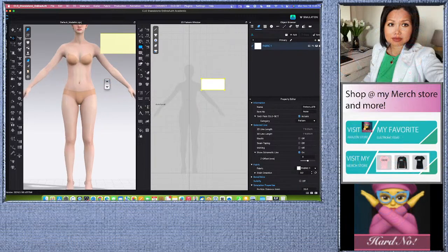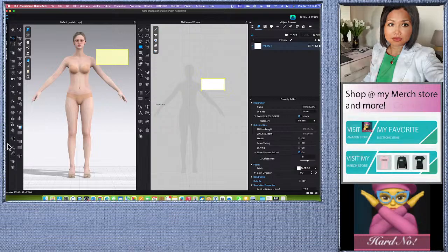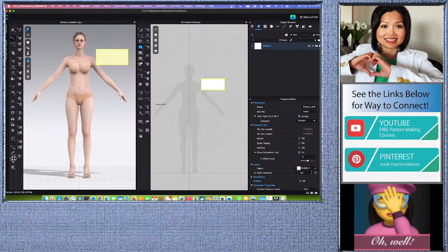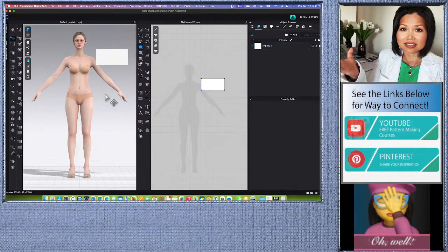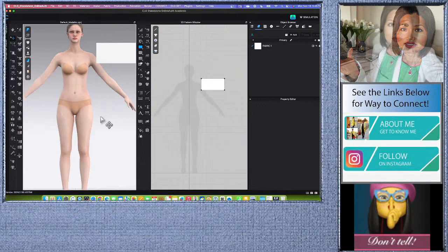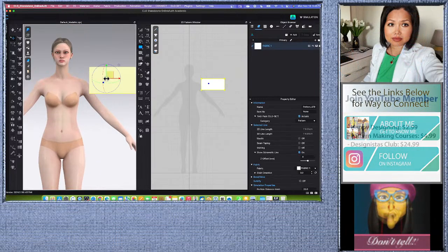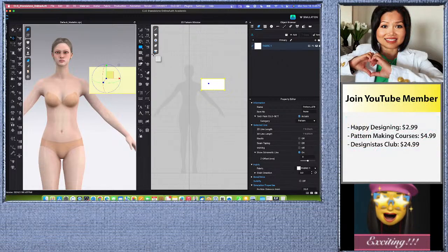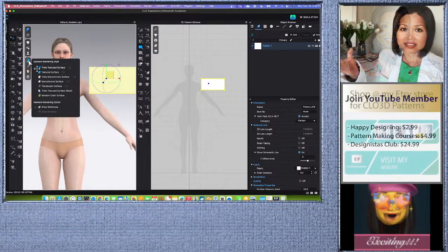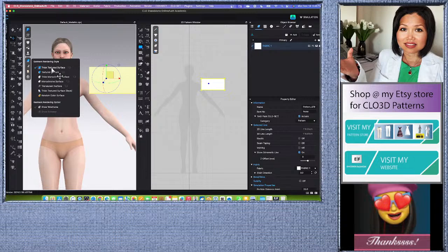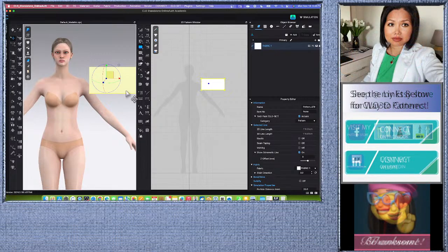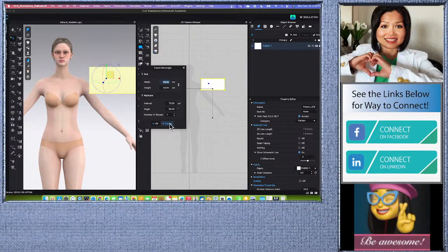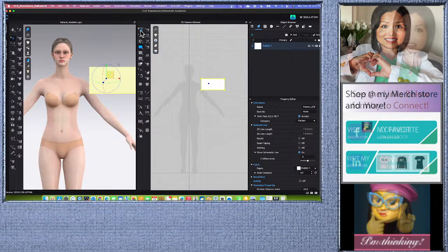Okay, all right, so right now we will come up here to this 3D toolbar. First of all though, I got a question about why you don't see the thickness on the fabric here. So over here in the vertical toggle menu, we want to select thick texture surface. Let me get out of that tool and go to the transform tool.